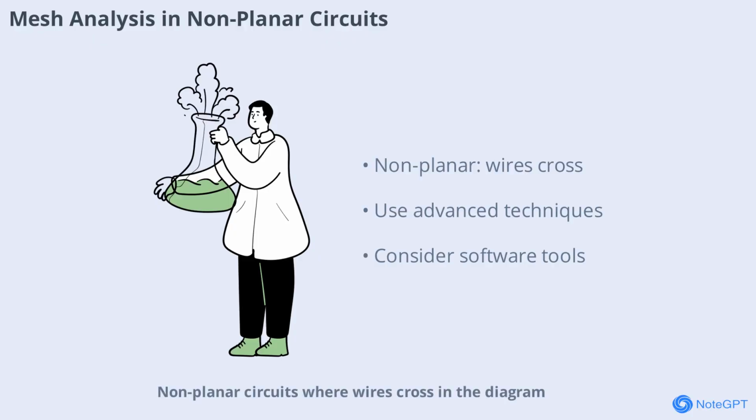Non-planar circuits where wires cross in the diagram are not ideal for mesh analysis. These circuits require more advanced techniques or computer tools for analysis. If you encounter a non-planar circuit, consider using nodal analysis or specialized software to handle the complexity.